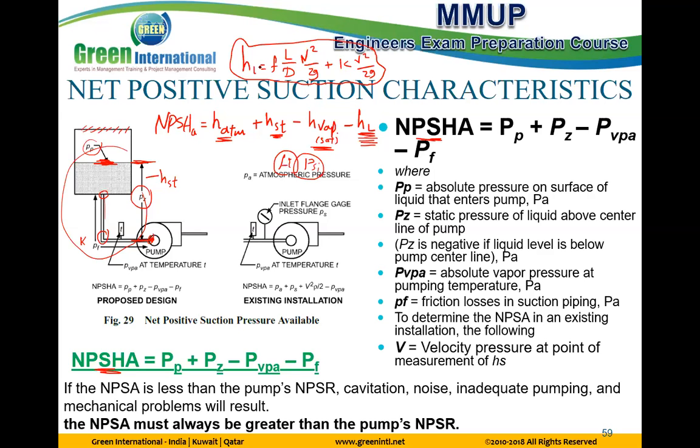So how do you know whether to calculate all of it or only one part? If the given information is for F and other pipe information, you calculate that part. If you need K and information for fittings, this one should also be included in the equation. Okay. Got it.